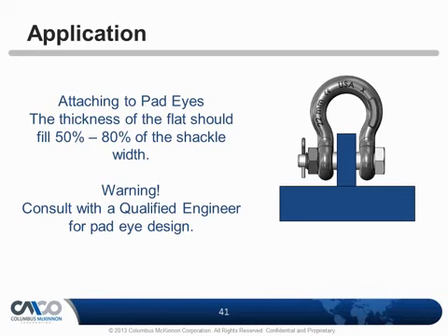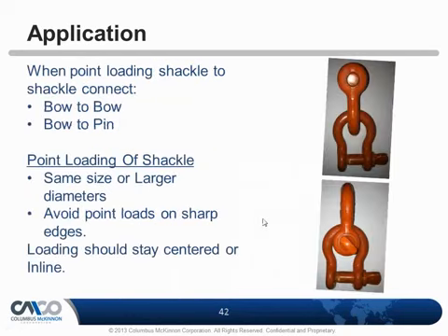So why would you spend all that money on the quality equipment that you have to lift safely, and then not worry about the lift point that you're lifting from? And that's common, and it's just kind of backwards thinking. It will always be your weakest point in the lift that's going to fail. So you always want an engineer to design a lift point. Right now, there really isn't any standard on lift points other than to get somebody qualified who can calculate the shear strength of that steel.